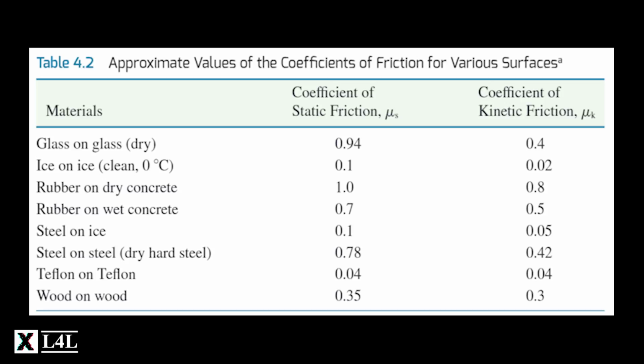Again, remember that kinetic friction has to do with the sliding of the material. So this would be where you're turning and you're sliding, the back tires start to slide out. That's when you transition over to kinetic when you're talking about your tires. And really, there are different types of rubber. The rubber that they use on a drag racing car on a track is going to be a lot softer, much grippier rubber than the rubber that you would see on your all-weather season tires on your car. Now you get a better grip, but those tires don't last as long. So there's a trade-off. The rubber compound would affect these numbers as well, but you can get a general sense of it.